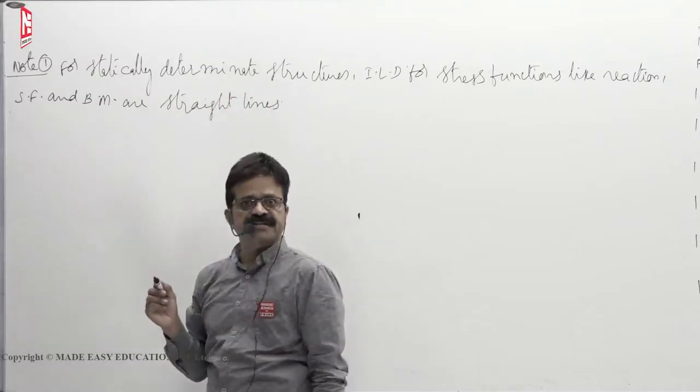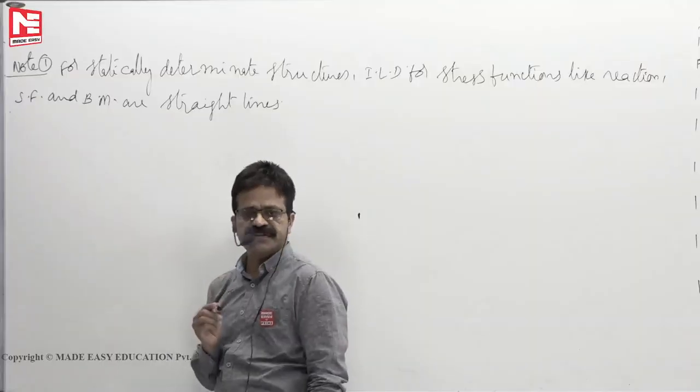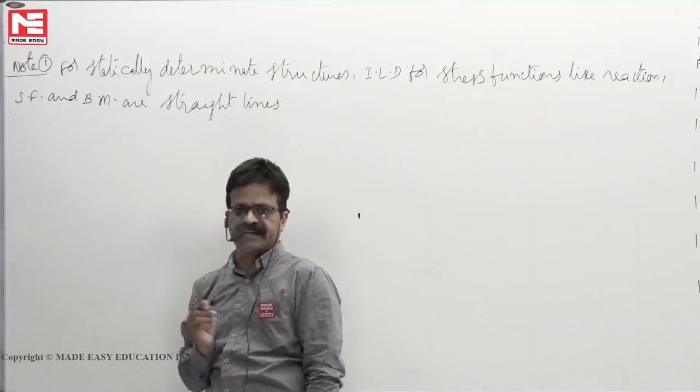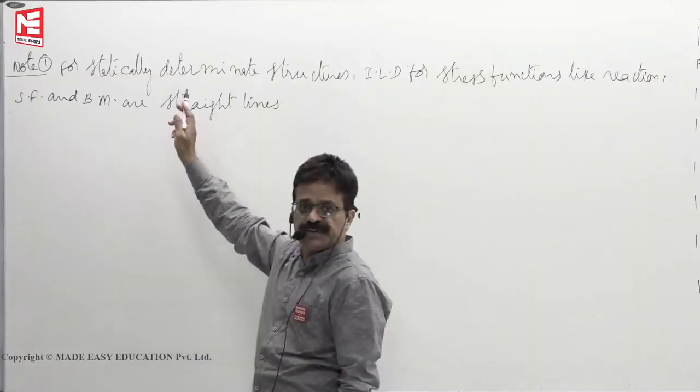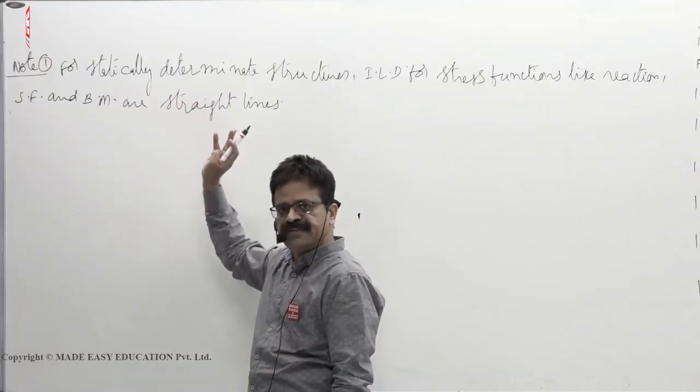For determinate structures, the ILD for deflection is not a first degree straight line, it is again a third degree curve. For stress functions only, reaction, shear force, bending moment, only straight lines.